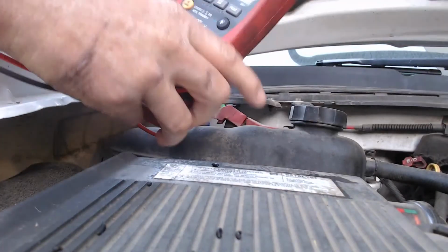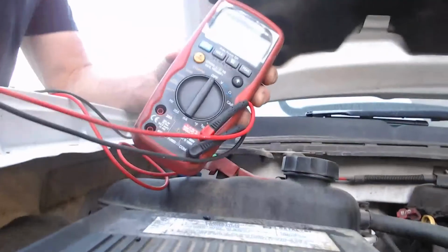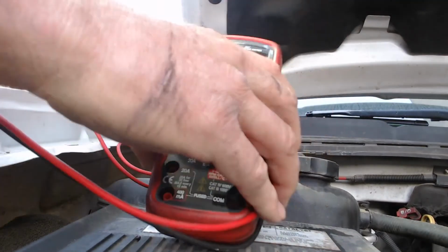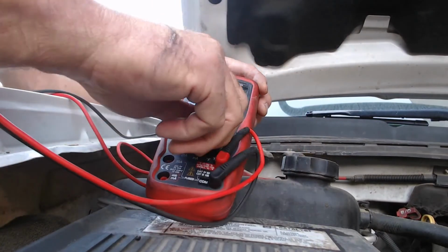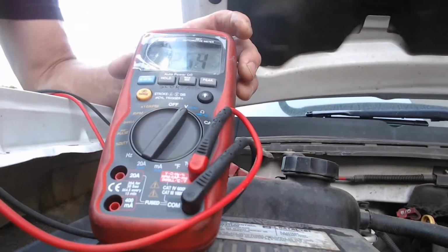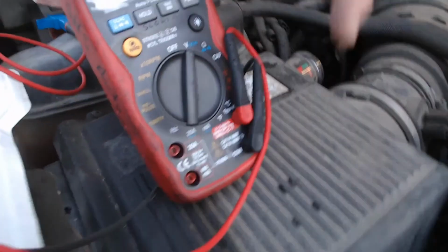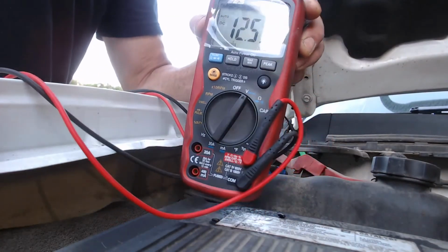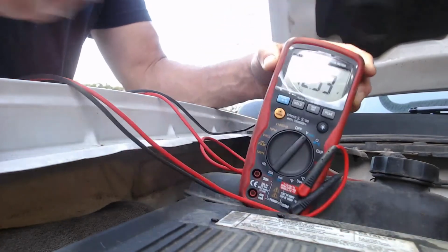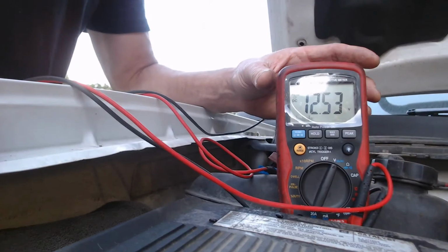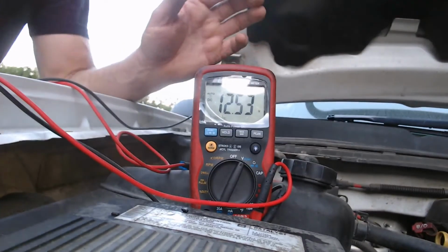Now what I'm going to do is I'm going to go ahead and start the car, and you will see the charging system voltage. We expect to see 13.5 to 14.5 volts. And right now we're resting at, look at this, we got rat poop right here. So obviously there's been rats living under this thing. But we're showing this thing at 12.53 volts. So let me go start it and kind of wedge it in here so you can see the screen. I will start it and we will see what we get.